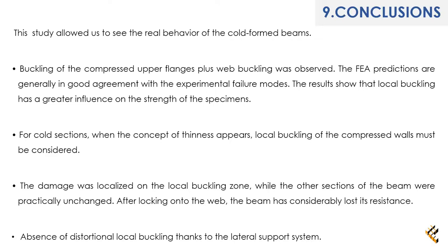Buckling of the compressed upper flanges and the web. For cold formed sections, when the concept of thinness appears, local buckling of the compressed walls must be considered. Absence of distortional local buckling thanks to the lateral support system.